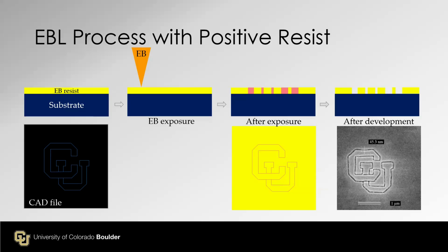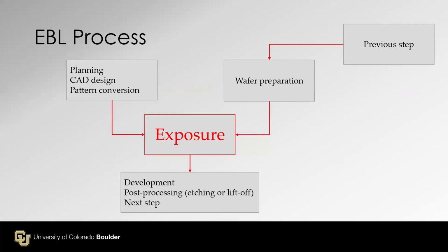Those are the differences. I did not do this lithography, but I found it, so somebody did it. Even though this is a converted SEM, and not even a field emission system but a tungsten filament system, maybe 30 kV or something, it's a very primitive E-beam writer, but you can still do 50 nanometer lines, thanks to electrons.